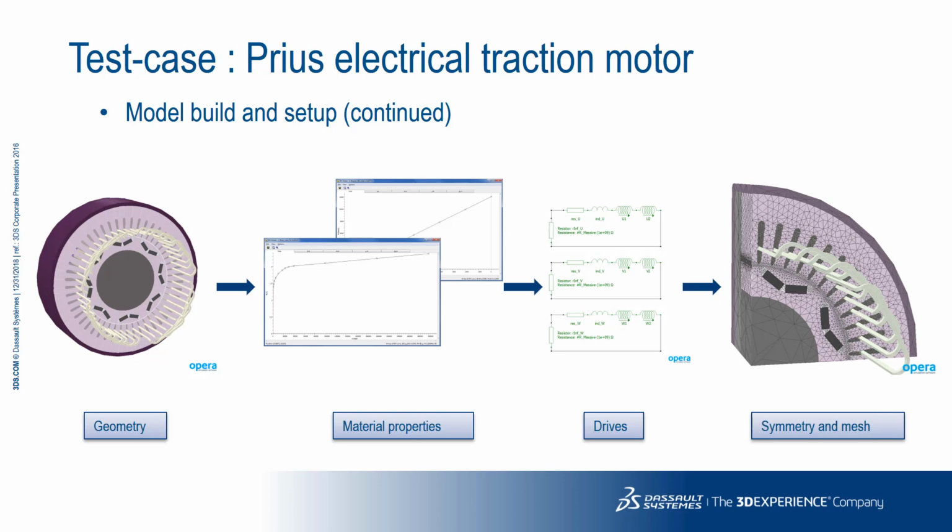The user only needs to specify the properties of the relevant components, for example phased resistances and inductances, parameters for voltage source, etc. Based on the topology of the device, the machine's environments will also determine the correct symmetry conditions so that the minimum required section of the machine is analysed in order to optimize the analysis throughput. The mesh is also handled automatically by the machine's environments with the use of scaled mesh sizes in the different parts of the machine.